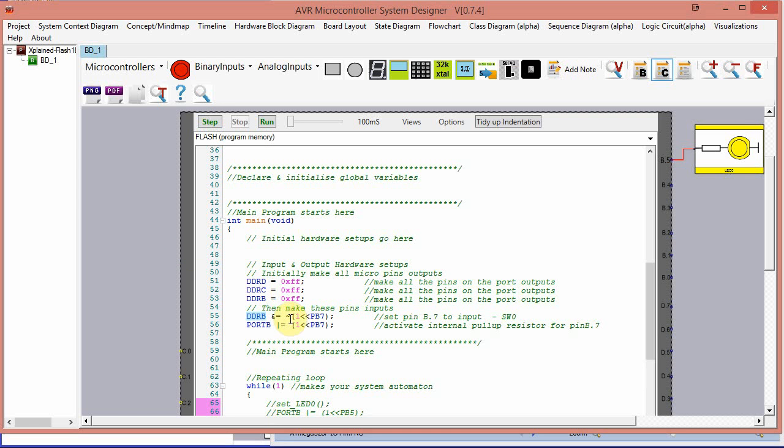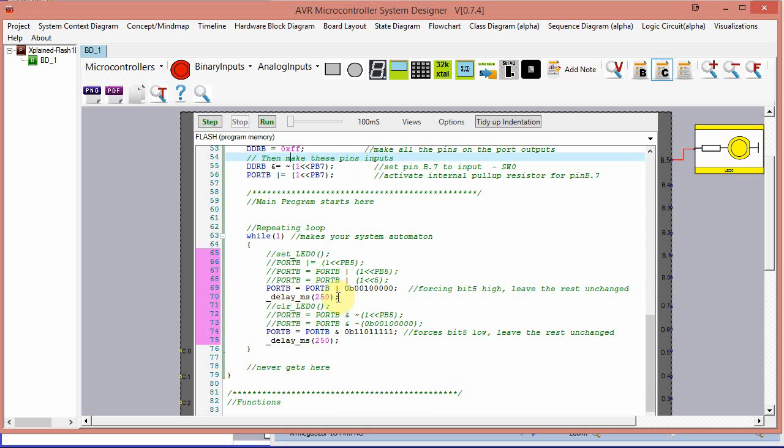So we've looked at a little bit of bitwise arithmetic. Remember, a port is 8 bits, so if we're going to OR it or AND it with anything, we need to do all 8 bits. And this line here, this little shortcut, is very common in C. We unpack that into this. That's a very common contraction in C. You'll see that everywhere. That's what it means.